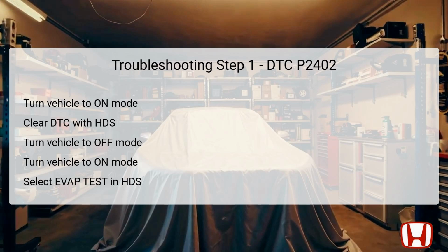The next crucial step is to select the EVAP test from the inspection menu on the HDS. By running the EVAP leak check module test, technicians can determine if the issue persists and if any high voltage readings or failures exist in the system. Successful completion of these steps allows for a clearer picture of the fault's nature.